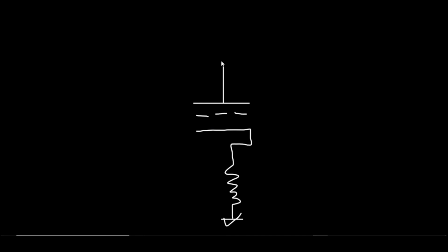Now the cathode mixed with the plate resistor is where you get your gain factor from in a vacuum tube. But remember, we're not trying to get any gain out of this thing. We want unity gain. We just want something that's able to drive our EQ, which in this case would be here.